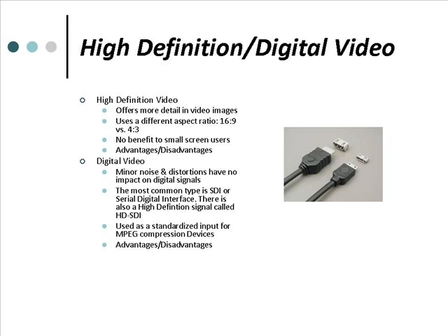The advantages of SDI video are it's a very robust signal, small variations in signal amplitude or noise can be ignored by the digital format. It's easy to transport and switch inside a production facility. Many converters are available for handling the changes to and from SDI and composite, and related signals such as digital audio or program-related data can be embedded into an SDI signal for easy transport and switching.